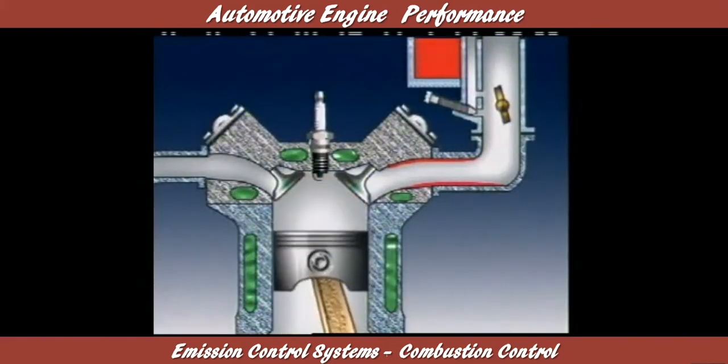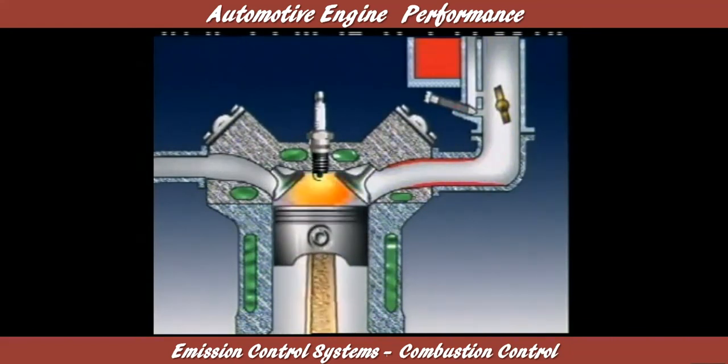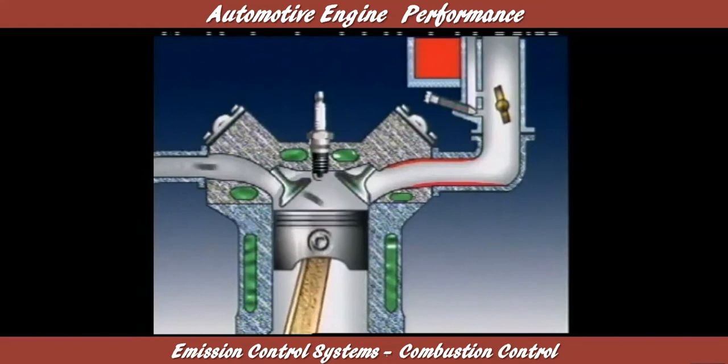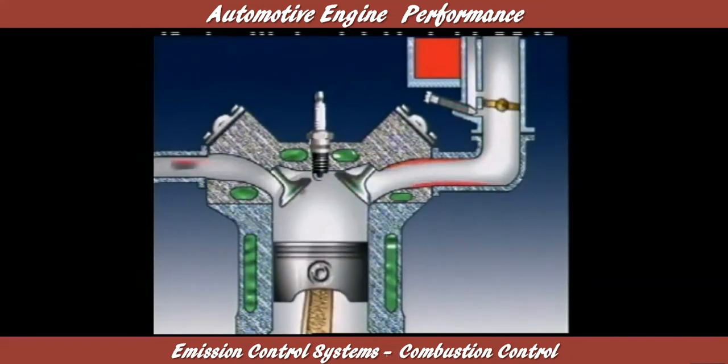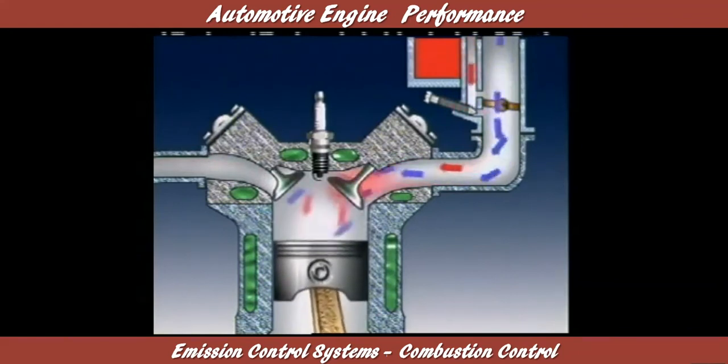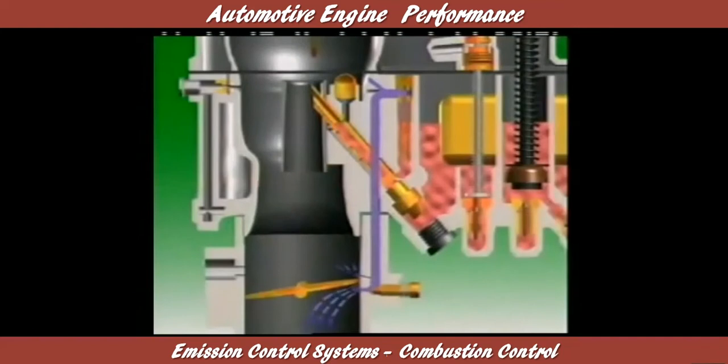Changes in operating conditions can change mixture conditions within the manifold. If a carbureted engine is being driven at moderate speed and the throttle is suddenly closed, any fuel condensed on the manifold walls is drawn into the cylinders. The low pressure in the manifold also acts on the idle circuit in the carburetor to cause a larger amount of fuel to flow from the idle discharge port. All of these factors enrich the mixture entering the engine.